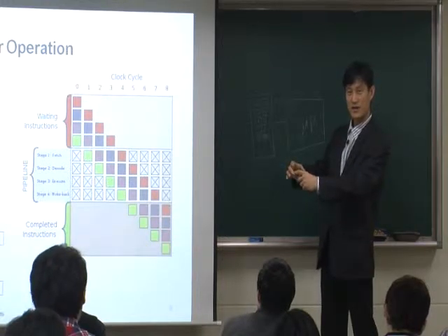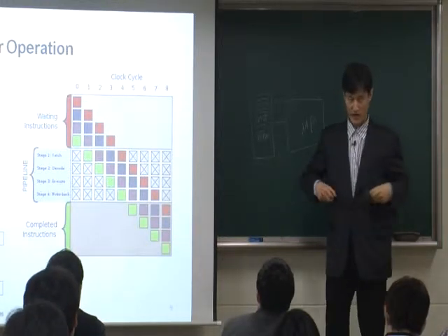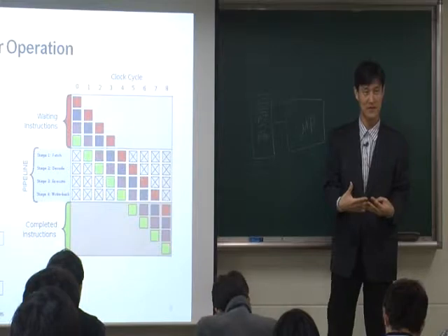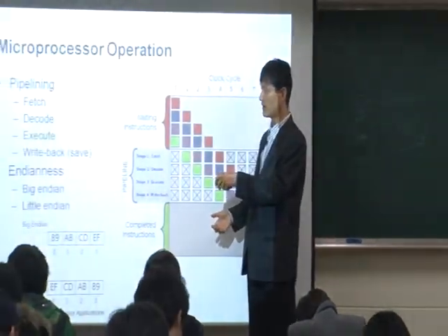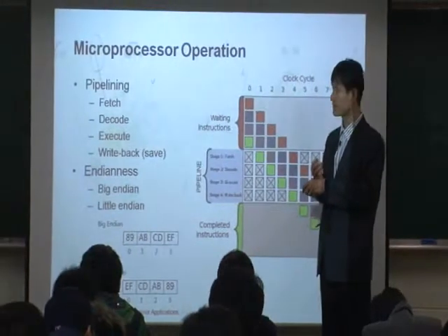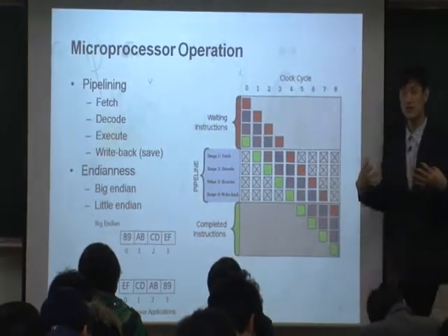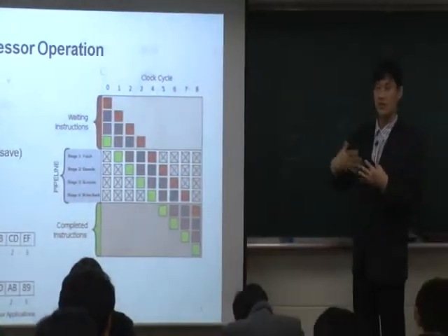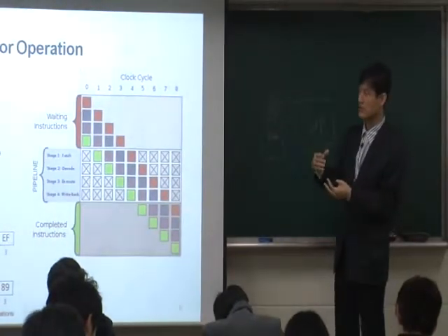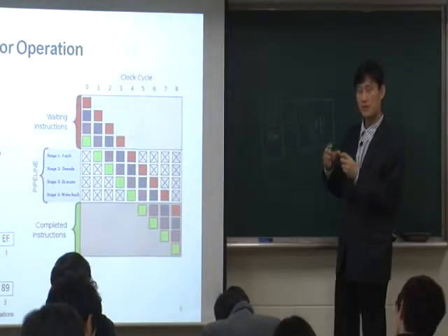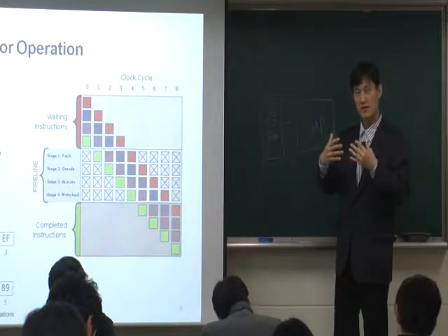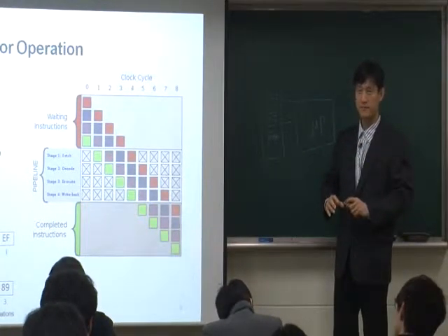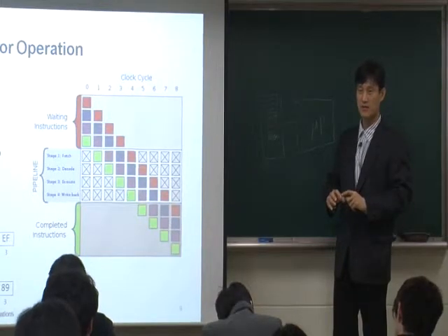That's decode. Okay? If this is add, then you actually have to do addition. The actual work, that's execution. Okay? That's a third step to do. Once you do execution, for example, addition or multiplication, depending on the instruction, then you will probably have a result, right? When you do addition, then there will be an outcome. There will be a result. Okay?